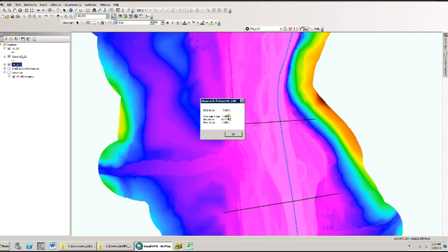End slope is obtained by calculating the absolute difference in elevations of the start and end of a line and dividing the difference by the total 2D length. The average slope is calculated by averaging the slope of all line segments after weighing each segment by its 3D length. This results in longer segments having greater influence over shorter segments.